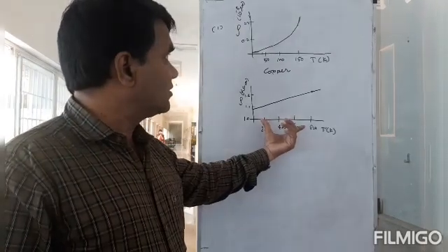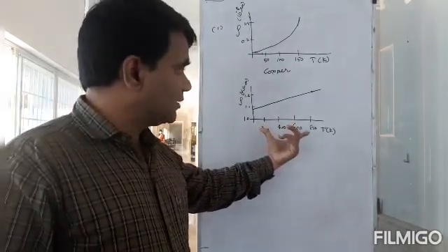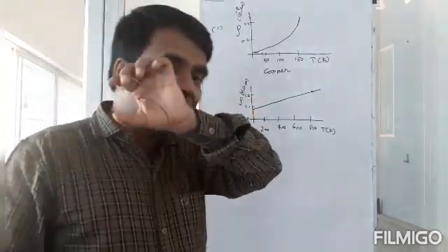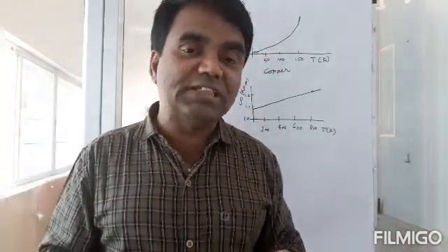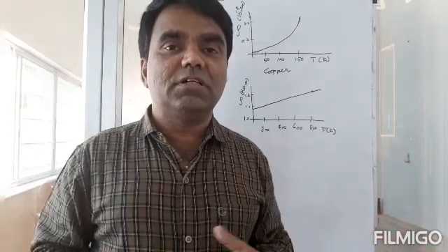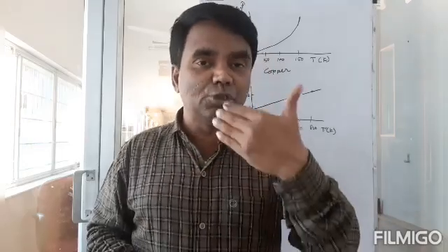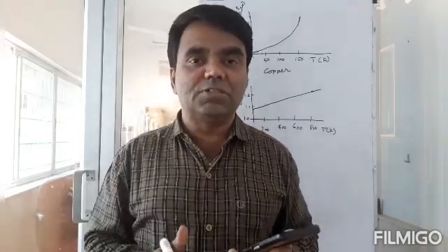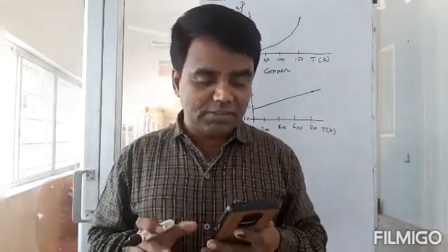But here, notice, over a temperature of 800 Kelvin, only 10% change. So the resistance will remain almost constant over a wide range of temperature. So increasing temperature doesn't really change the resistance of these materials. And these materials are going to be used in instruments like meter bridge and potentiometer, and those are things that you will come across. They are used in electrical instruments where you want resistance to remain pretty much the same. So this is for Nichrome.